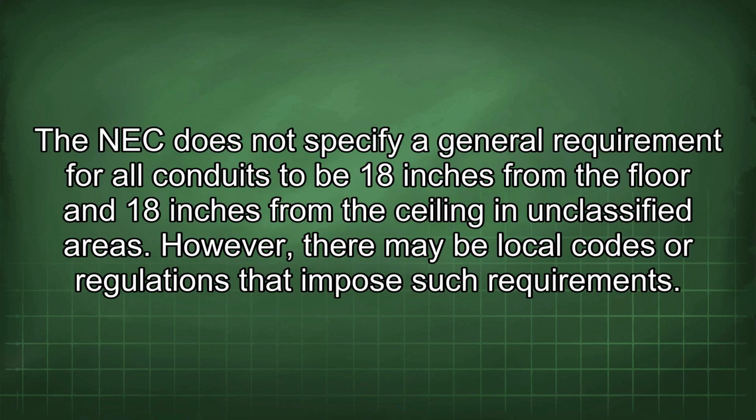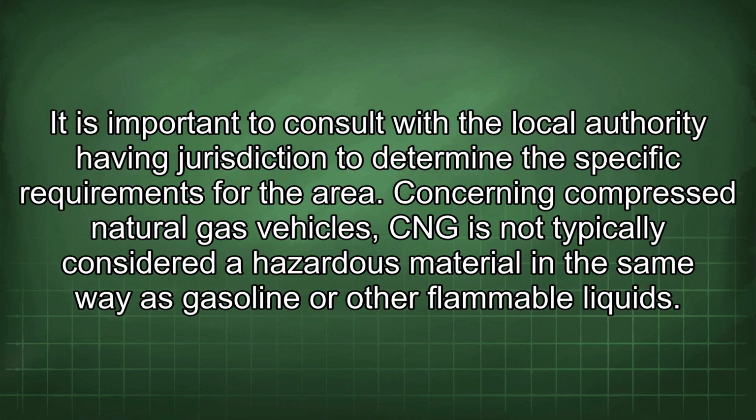The NEC does not specify a general requirement for all conduits to be 18 inches from the floor and 18 inches from the ceiling in unclassified areas. However, there may be local codes or regulations that impose such requirements. It is important to consult with the local authority having jurisdiction to determine the specific requirements for the area.